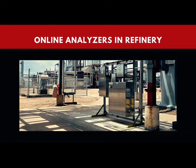Apart from the laboratory analysis, there are online analyzers inside the refinery. Why at all do we need online analysis inside a refinery? When you send a sample to a laboratory, it is going to take time to get the results. There will be huge latency to know the results of a particular stream.